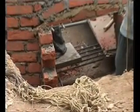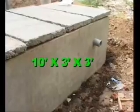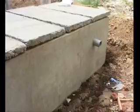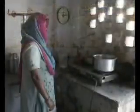After the construction of the biogas plant, the outlet tank is constructed. The size of the outlet tank is 10 feet by 3 feet by 3 feet. 2 outlet pipes are fixed in the outlet tank to drain out the excess slurry. Similarly, a circular inlet chamber is constructed to feed the biogas plant. After the completion of the biogas plant, we make a connection of the biogas plant to the kitchen.